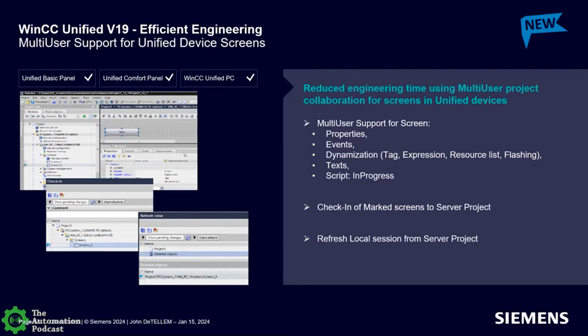Another thing that's pretty significant was rolling the unified engineering into our multi-user support. So that multi-user project server functionality had been part of the TIA Portal framework in the past, but when we introduced Unified, there was a slight gap from one release to the next in its feature set, supporting the ability to check in and check out changes across multi-users. So v19 really brought forward that ability to work on a project server, or work by myself and check in my changes and keep track of them with the project server.